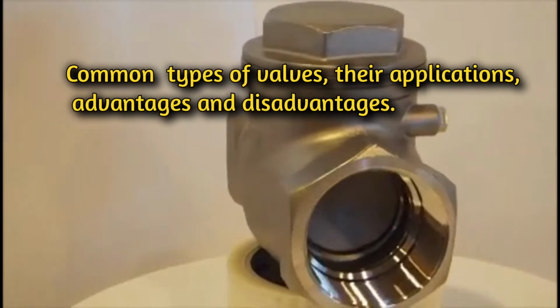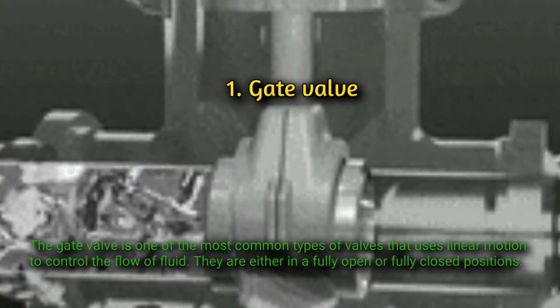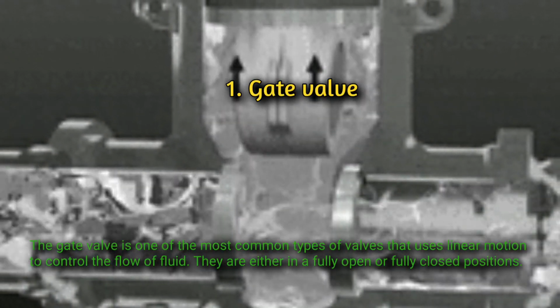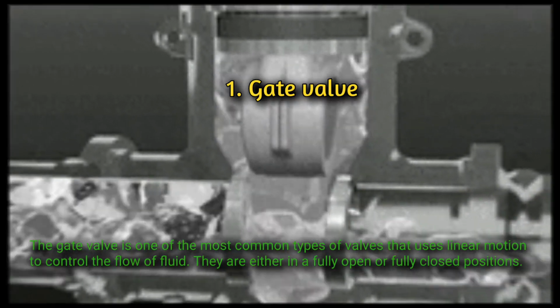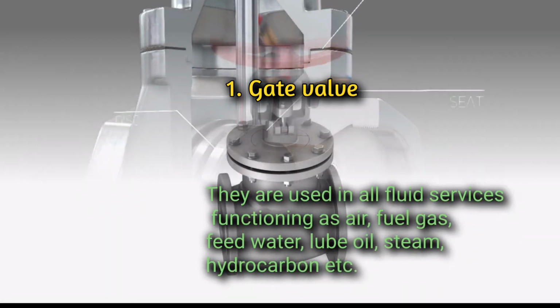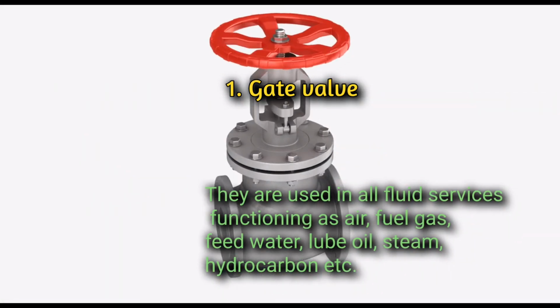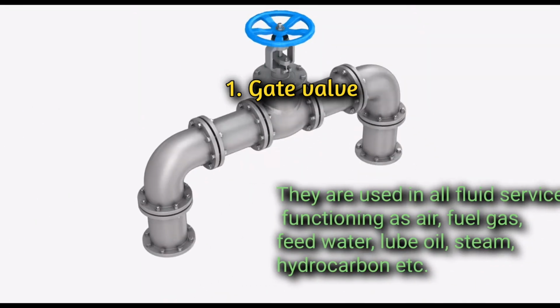Common types of valves, their applications, advantages and disadvantages. Gate valve. The gate valve is one of the most common types of valve that uses linear motion to control the flow of fluid. They are either in a fully open or fully closed position. They are used in all fluid services such as air, fuel gas, feed water, lube oil, steam, hydrocarbon, etc.